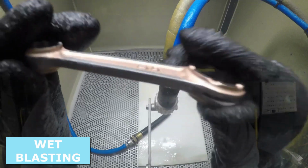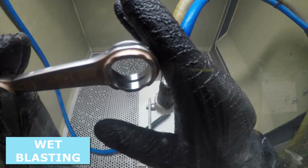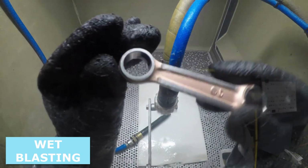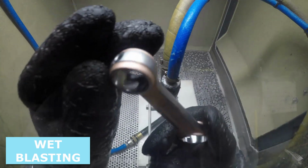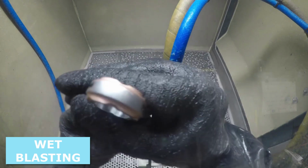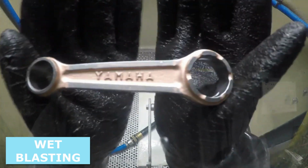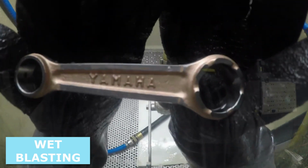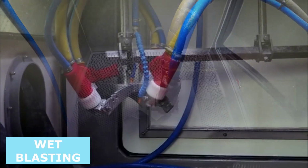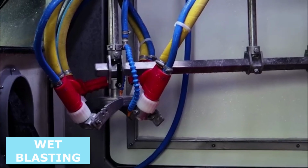Vapor blasting has become a top priority for many automotive and motorcycle workshops. Why? With vapor blasting, you can clean, restore and protect in one simple step using wet blasting. With the flow-based, topography-following nature of wet slurry, you can clean corrosion, oxidization, carbon, rust and years of grease and tarnish out of the tightest places. No other process compares when it comes to not only cleaning but surface finishing parts for a rebuild or partial restoration.